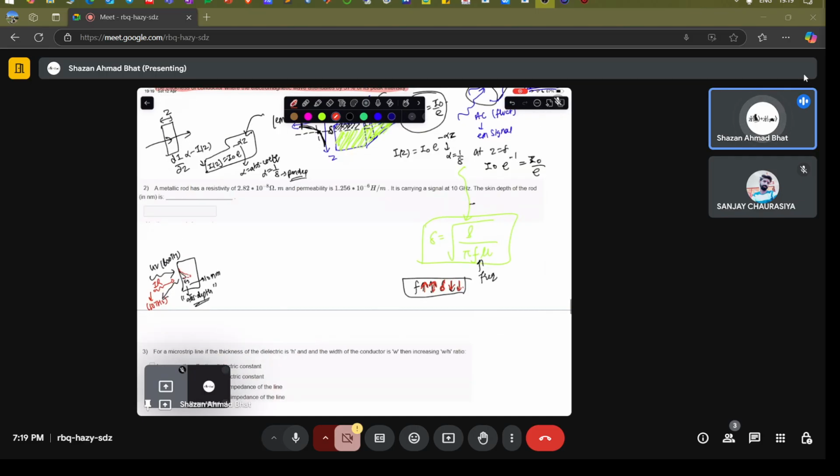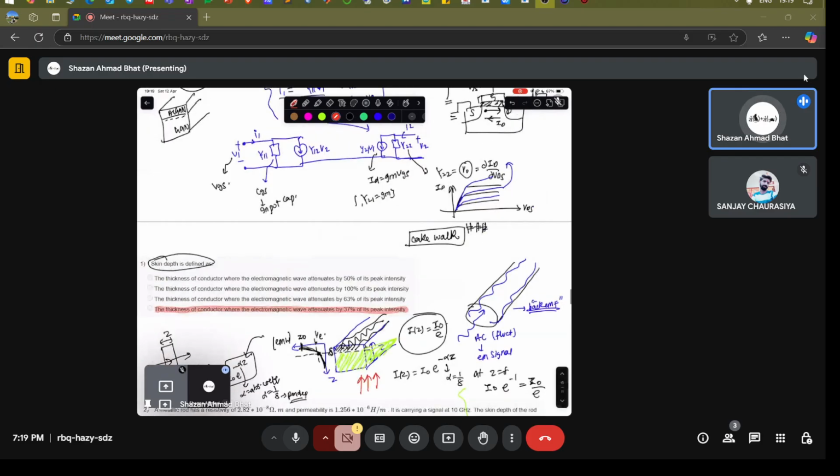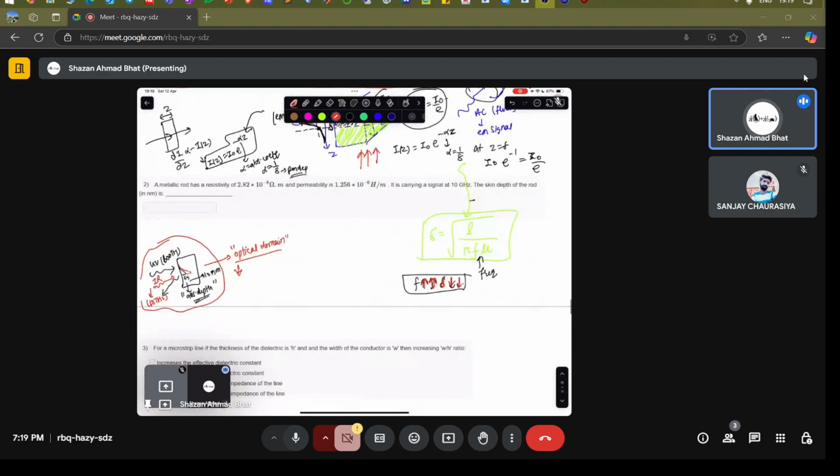Okay, so that is the effect with this particular frequency. But in this case, it is more because this is an optical domain. The effects are similar, the physics is similar, but in these microwave devices, because they are carrying currents, it's because of the back EMF generated. But in the optical domain, this effect is mostly because of the real part of the refractive index plus the imaginary part of the refractive index comes into the picture.